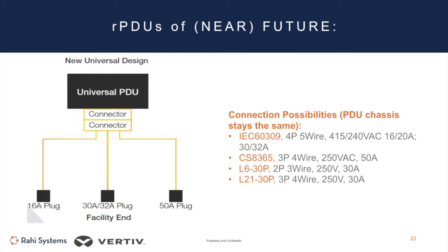We used to have three-phase banked receptacles. So you can see this is bank 1, bank 2, then identified by the colors here. And we talked before about the alternating receptacles. So we have 1, 2, 3, 1, 2, 3 that repeat throughout the chassis, and you can see that corresponding to the colors down here. So we've gone from banked to alternating, providing the virtue of inherent balancing.